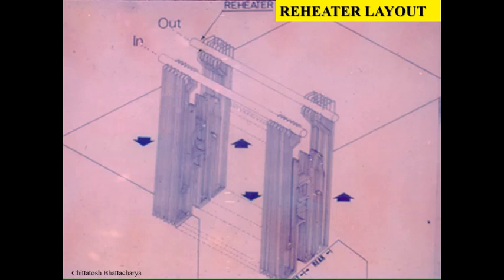Say if the final superheater outlet temperature is 540 degrees centigrade, the reheat temperature is taken back to 540 degrees centigrade, and this superheated steam at lower pressure, meaning the degree of superheat is more, is sent by the hot reheat line to the intermediate pressure turbine for further useful work extraction.